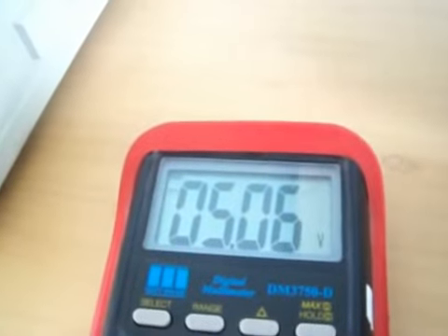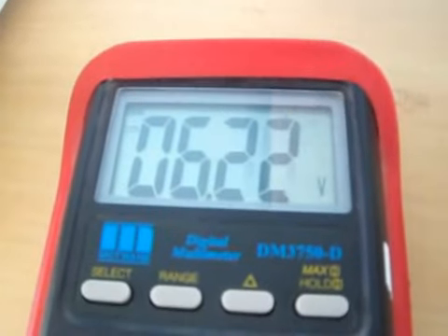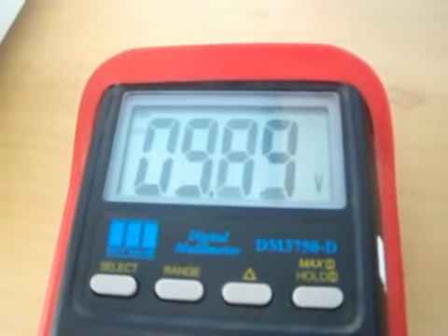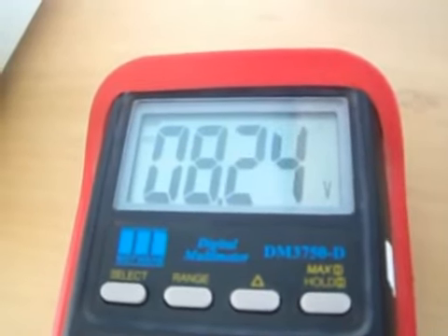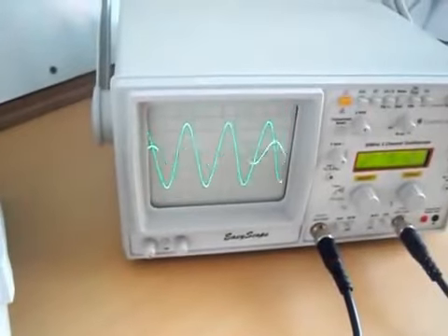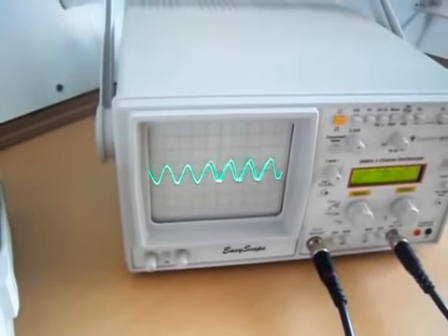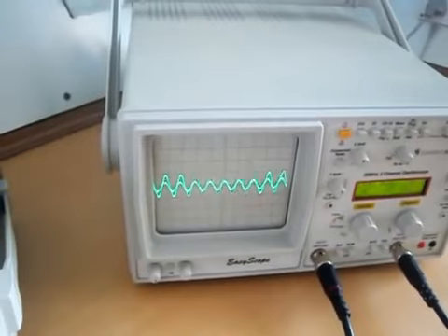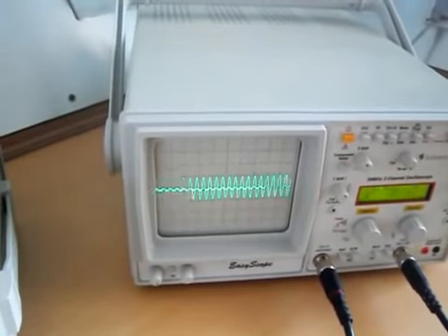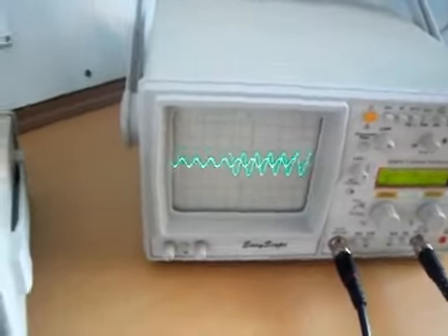Same way we are doing for control voltage of 8 volts, wherein the 8 volts has been controlled and is obtained on the multimeter. Therefore, from this it is clear that when the control voltage is kept at 8 volts, the output voltage doesn't increase more than 8 volts. It always falls less than 8 volts. And hence, again, when the frequency is increased from 100 Hz to 1 kHz, the waveform is shown on the CRO. As a result, as the frequency increases, the output voltage decreases, and the phase difference between input and output also decreases, which is shown in degrees.